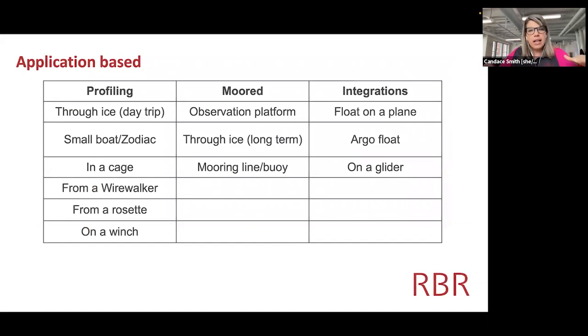So really, that was many, many different ways of deploying a CTD. But here at RBR, and I think in most places, we really would define those as 3 different applications. And I've said the word a few times of profiling. So just for everyone's benefit, I know this is probably preaching to the choir, but profiling really usually means you're going out some way onto the water, and you're doing a profile. So you're getting from, say, the surface down to a particular depth and back up of CTD information to get temperature, salinity, density, depth. So these are all kind of how we think of it at RBR, the same sort of application. So they're all profiling.